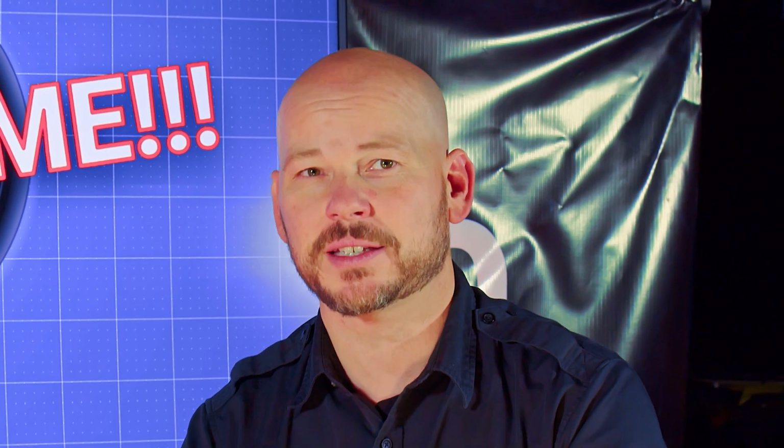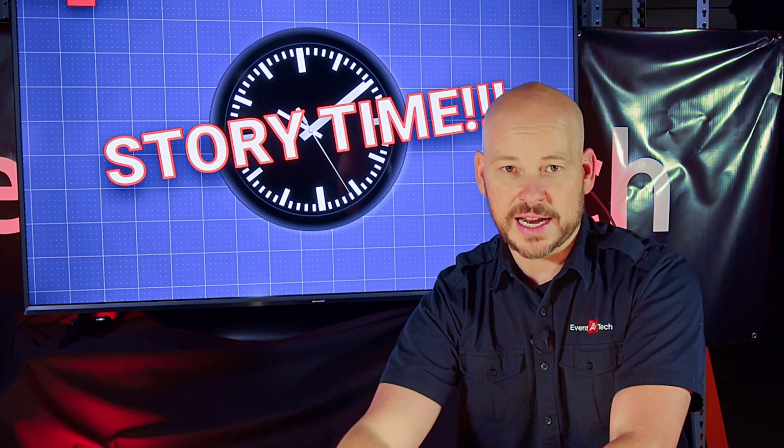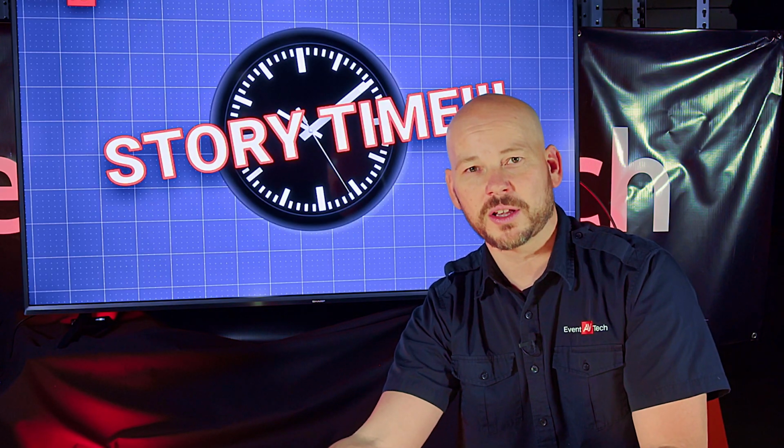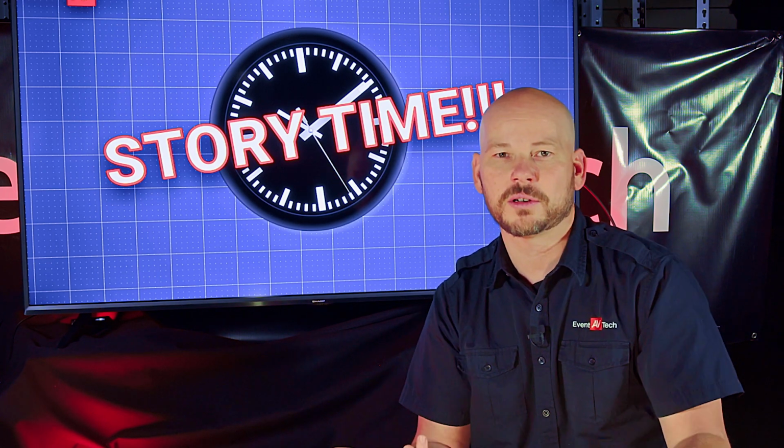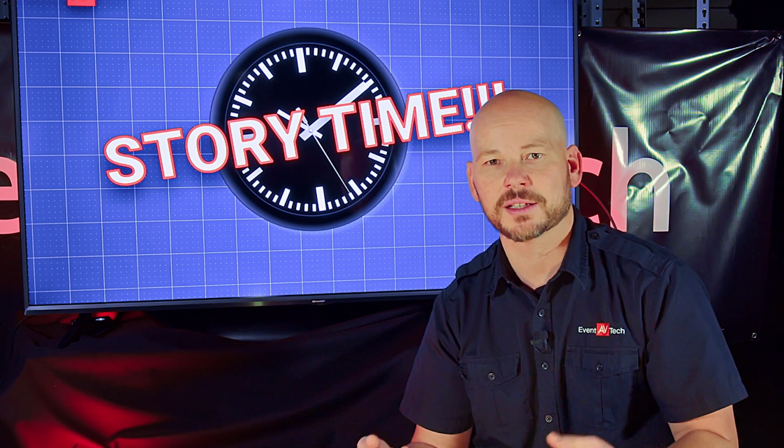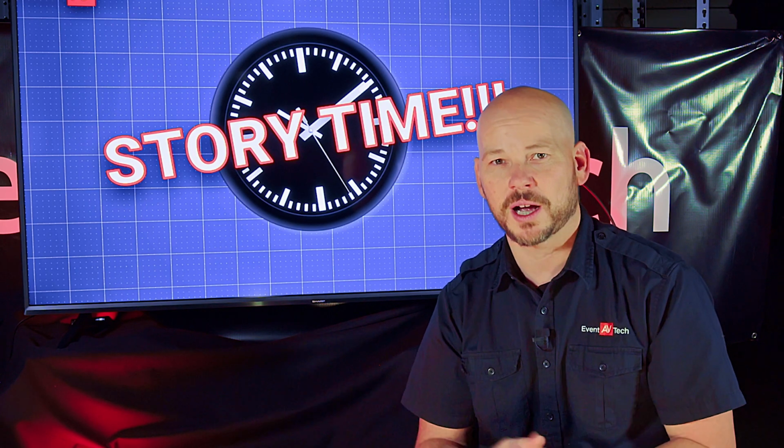And I immediately said, oh, your house lights are plugged into the wrong panel box. And they started laughing. They're like, well, how do you know that? You haven't even looked at it. So they go over to the lighting console and they turn on the lights, and sure enough, it begins to buzz in the audio system. And I said it again. I was like, well, your dimmer packs or whatever's running your lighting is plugged into the wrong panel box.